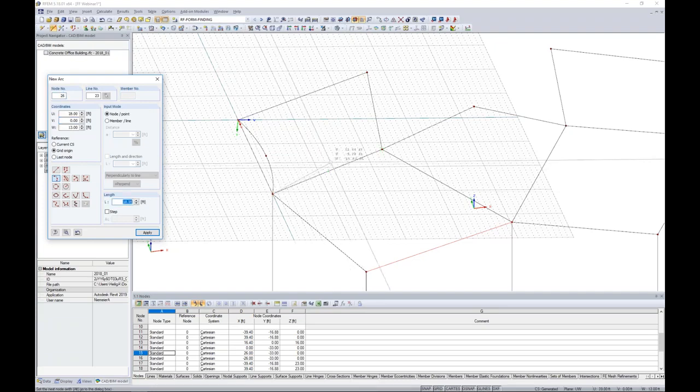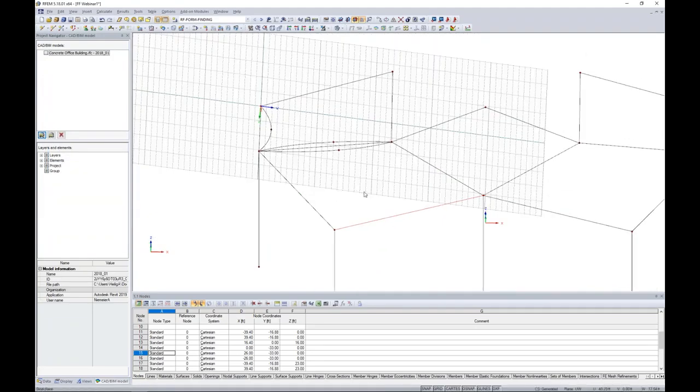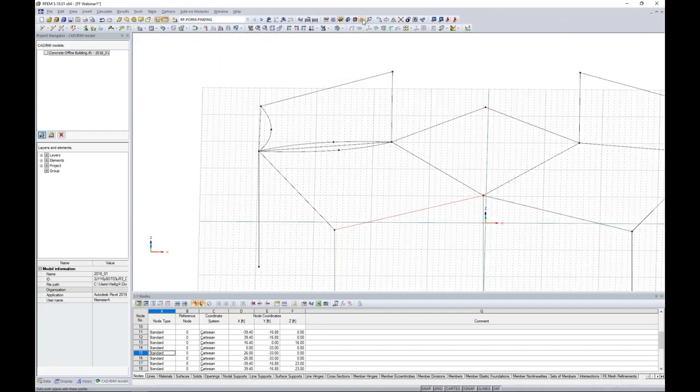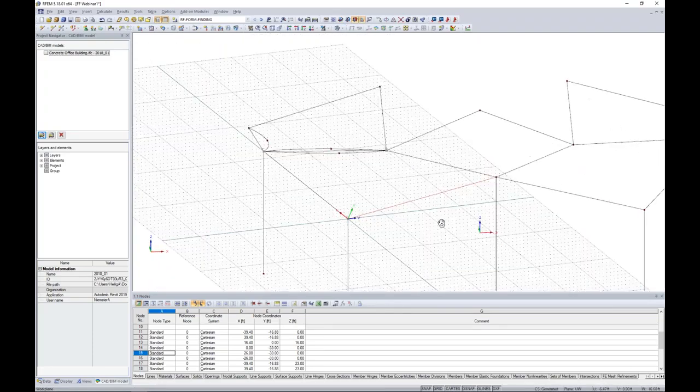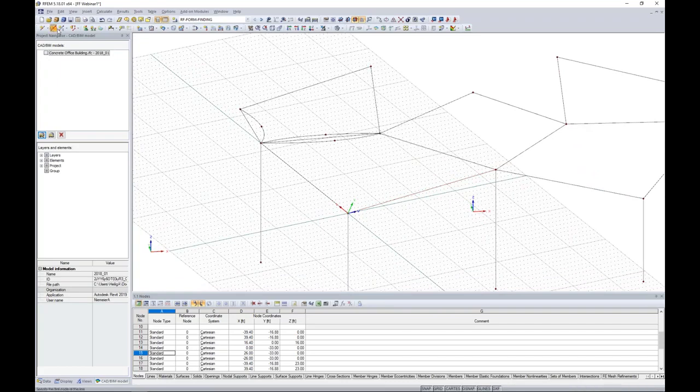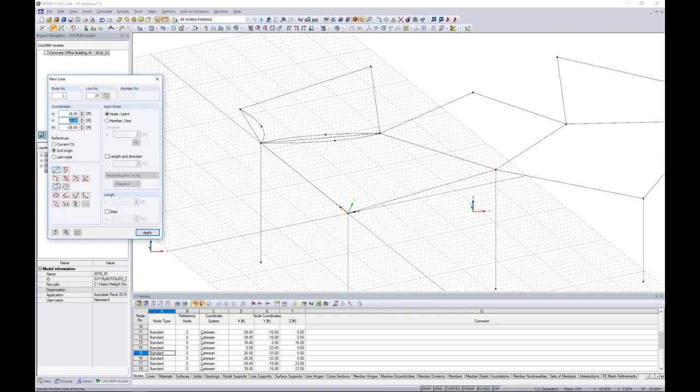I'm going to do the same thing at a different location here for my cell points. Again, completely arbitrary. We need to move up to the second cell, and we need to change our user-defined drawing grid. I click first to reset the drawing grid, click it again to define my new point, and I can click on 3 points here. Now you'll notice that I have a new drawing grid at a specified angle. So we draw a new arc, and I can simply snap to these points, again, any arbitrary points.